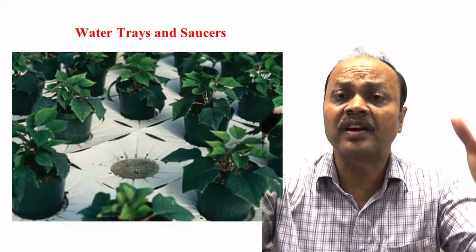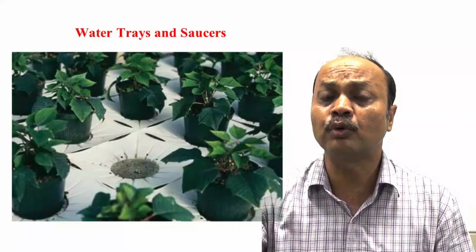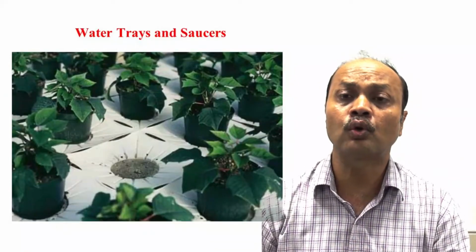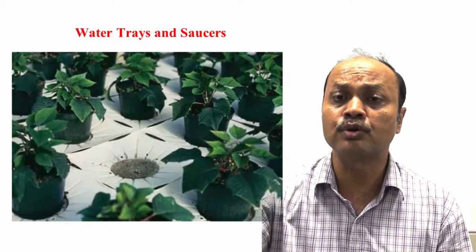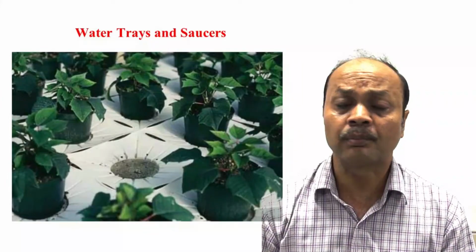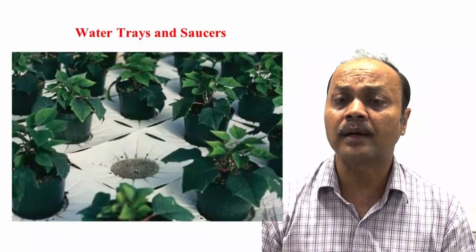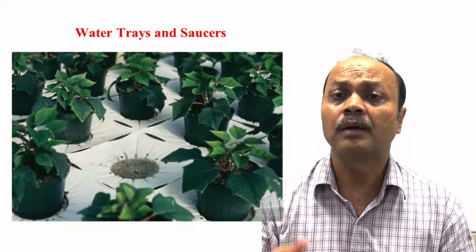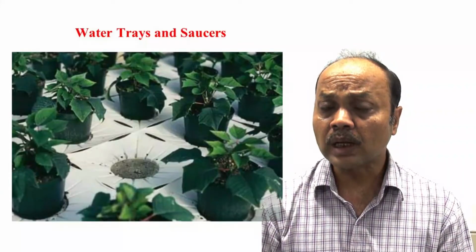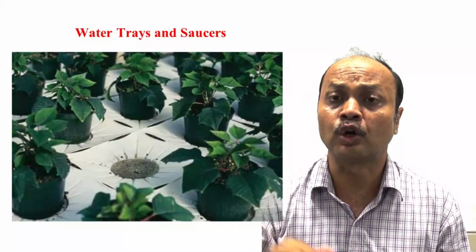And there are different types of filtration systems. Your filtration system will be selected based on the quality of your water, right? And then there are different types of fertigation systems. You will use the different types of fertigation based on your requirement, because as I told you, Venturi is one of the low cost options, right? So you start with the Venturi, and normally the pump system is used for a higher area for more control, right?